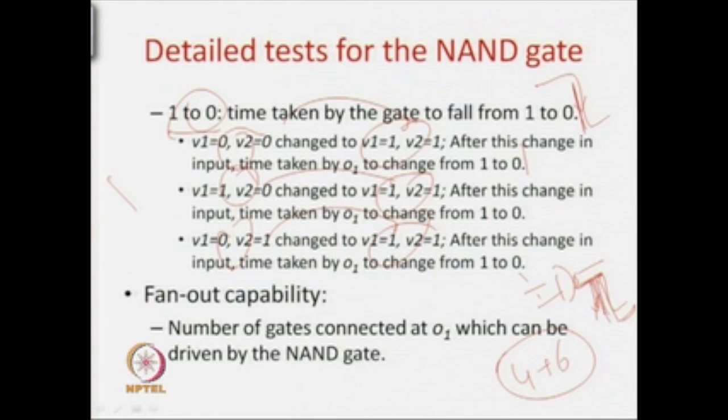Now, the other important thing which you sometimes take into picture is that this is your NAND gate. I think you might also have seen the fan out case in our previous modules, that this NAND gate can drive or needs to drive several other gates. Now, the question can be asked how many gates, or what is the fan out capability or the drive capability of this NAND gate. I am not going into details of how the test can be done, because it requires some complexity to perform, but again you have to tell that these gates can pretty well drive so many other gates with so much load in so much time. So, this is about the fan out capability test.